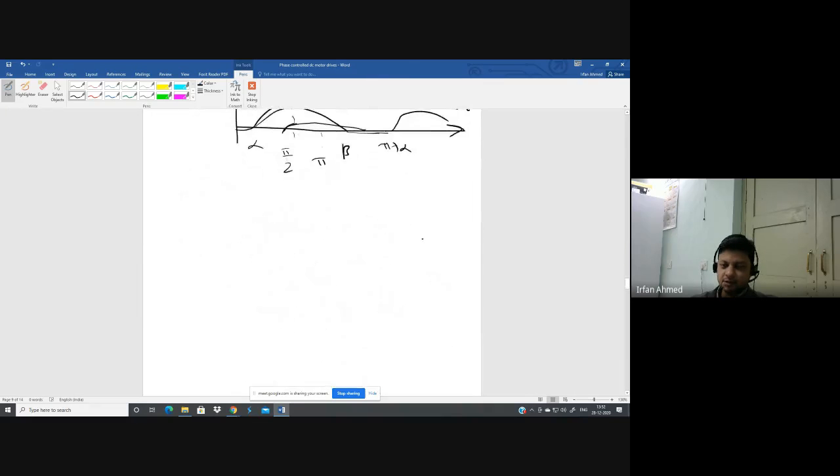Okay, basically they teach this to you in first year. So the armature current has one steady state component because of the AC supply, that is Vm by Z sine omega t minus phi. Correct?